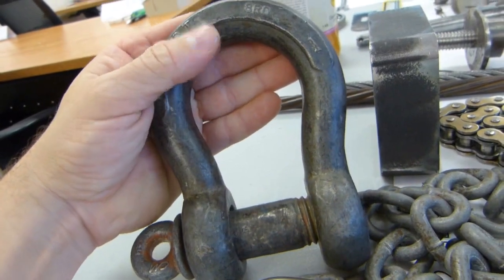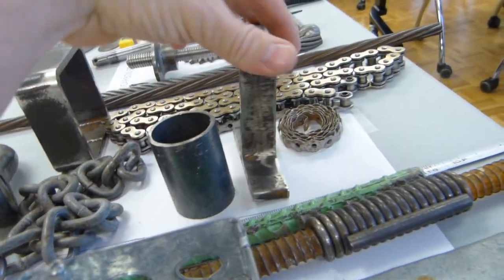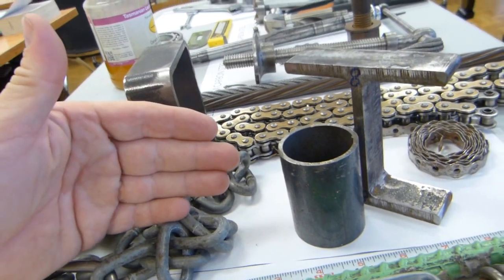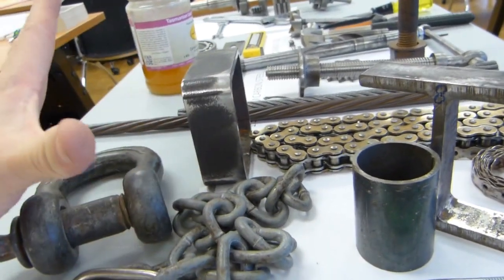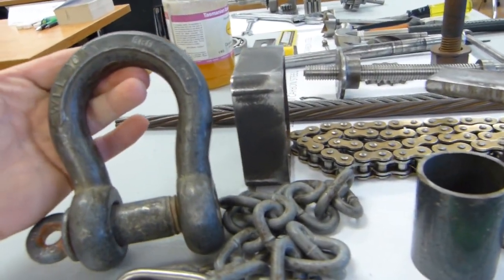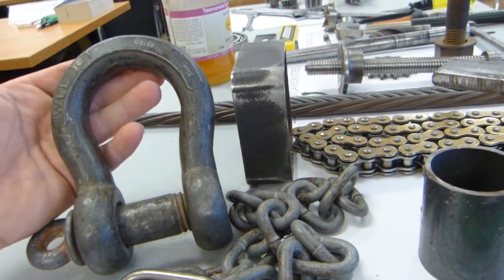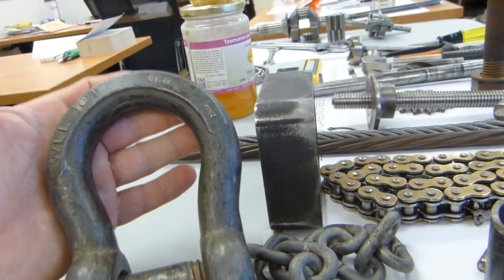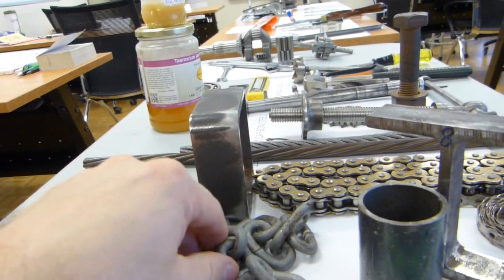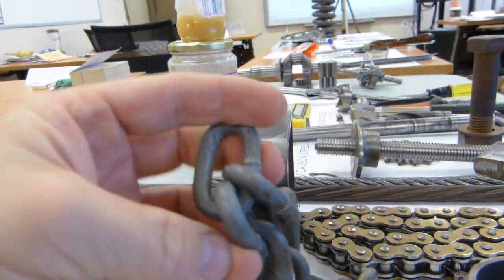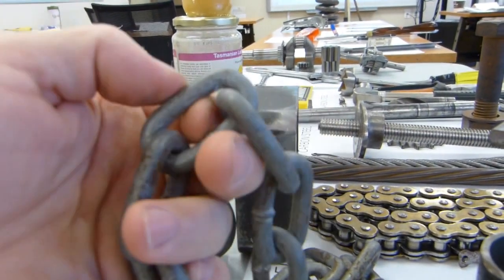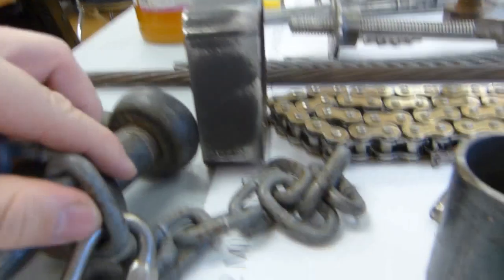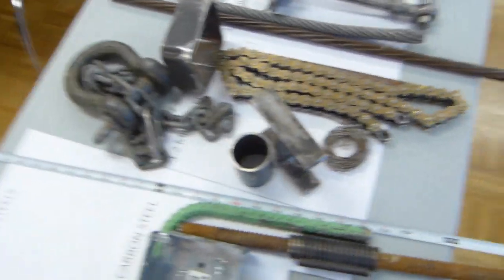The point of this product being made out of mild steel, or I-beams and these kinds of things, is that they bend and flex and deform visibly a lot before failing, instead of snapping suddenly without any warning. For safety reasons, these should be able to visibly deform, so it can be seen that they obviously underwent some overloading. To make this overloading visible, these have to be made out of mild steel. Same applies to chain. These links have a lot of stretch to them. If these links are visibly deformed and elongated, you know that the chain has been overloaded. So that's why they make them out of mild steel.